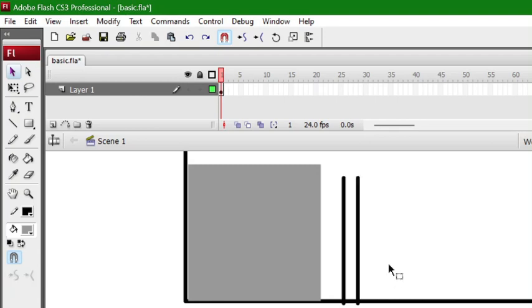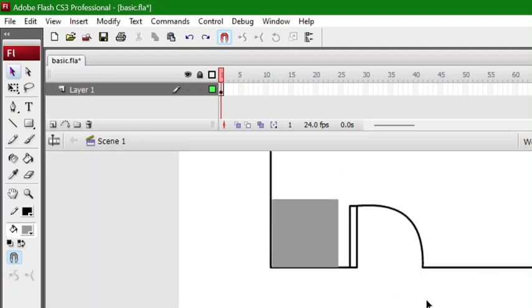And then click on the white background, click this one to copy the small parts of the line, Ctrl C, and then press Ctrl Shift B to paste in place, then Shift arrow up to move upward. Okay, and then we need to remove the excess line. And then project a line from here, click, and then position, click, drag, and then use the selection tool to make a curve. Then click this one, and then press delete. So this will be the open door for the entrance.